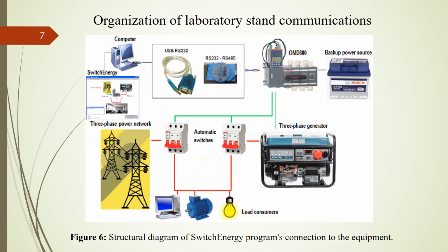The communication connection between AMD device and computer is created by means of required converters, the type of which depends on the computer configuration. Communication between AMD device and computer takes place according to the Modbus protocol, where the main device sends the request to which the involved device responds as specified in the request. Schematic implementation of the operation of the presented automated system equipment is shown in Figure 6.